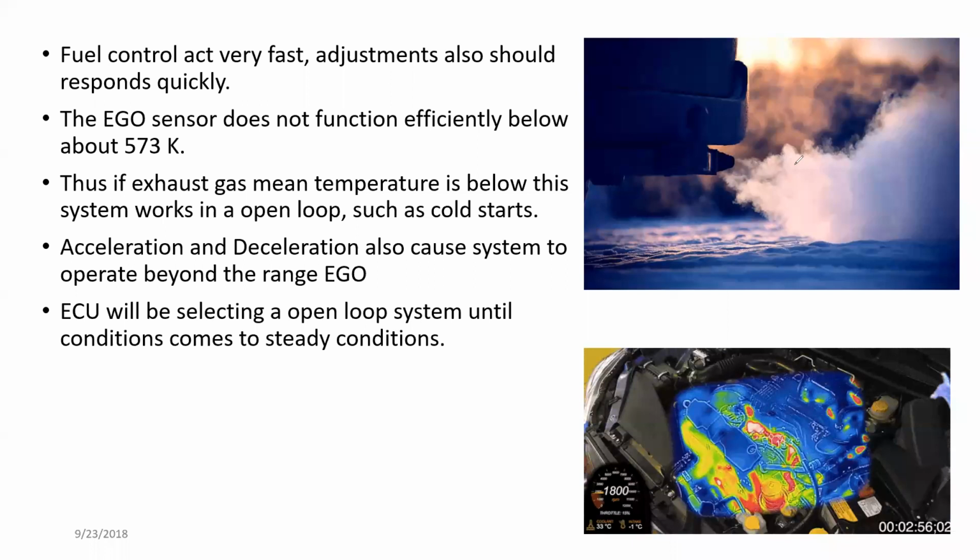As a result, engines heavily smoke on cold morning starts. But once the engine comes up to temperature and starts to get feedback, once it turns into a closed loop control system, the engine will trim the fuel supply and maintain very good combustion. So the smoke coming out of the engine will also reduce.